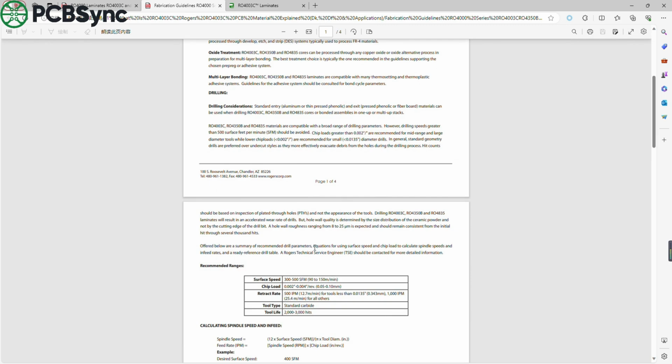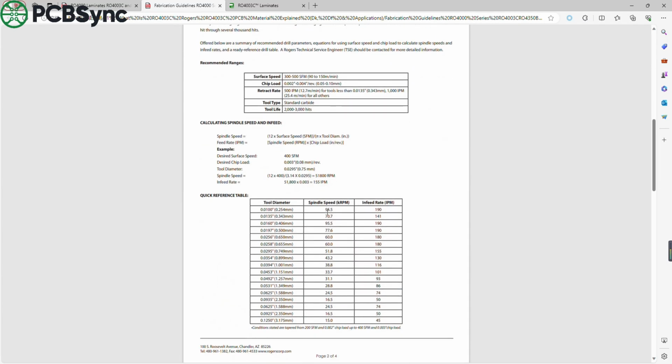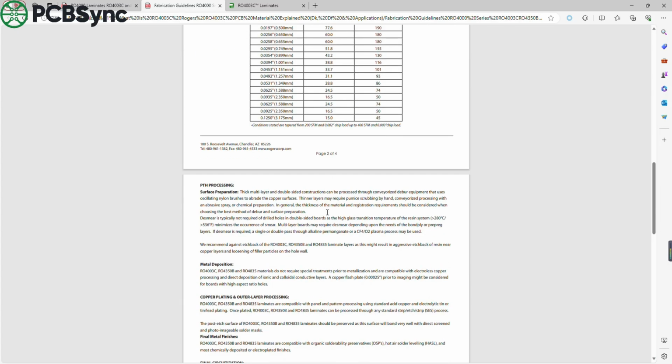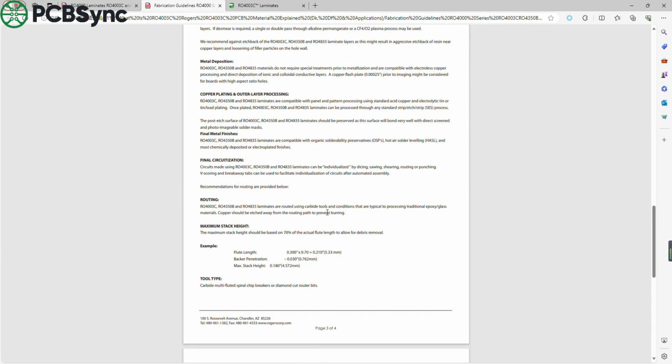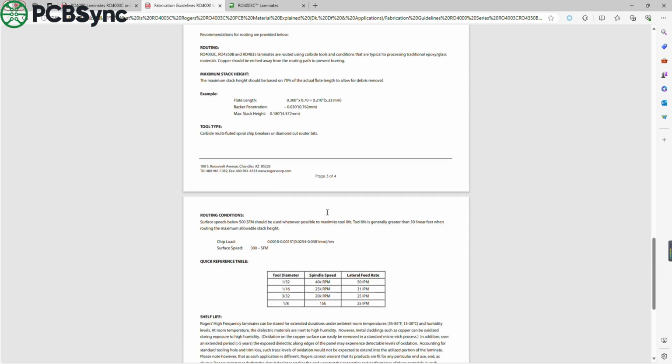Secondly, in terms of processing, RO4003C does not require any special treatment before metallization, and it is compatible with chemical copper and direct metallization processes. However, this doesn't mean that all FR4 production processes can be directly copied. In actual production, you still need to adjust according to board thickness, copper thickness, stack-up, and hole diameter, and re-establish drilling, lamination, and impedance compensation parameters.